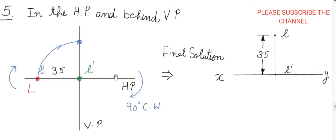Point is lying somewhere here, but is denoted as behind the VP. Now the point is lying somewhere here, shown by capital L with a red dot. When the observer sees this point, the front view is projected right on the origin and denoted by green small l dash. This is the front view denotation, and the top view lies itself on the HP. So small l denotes the top view.